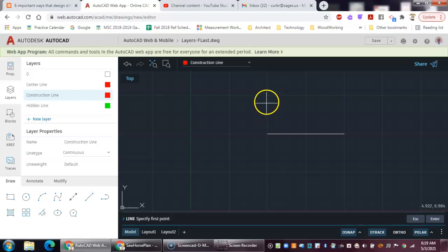Let's make this one 5 again in the X, and we'll hit the tab or the comma button here, and we'll make this at 5,10. So we're just going to allow a Y spacing of 5 on each of those. Hit enter. So we see the line now, lo and behold, it's out of our viewing area at this point.